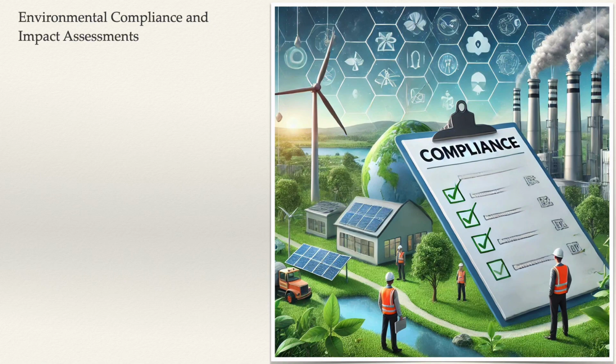2. Environmental compliance and impact assessments are typically conducted by the client before project initiation to secure route approval. For transmission line projects with significant environmental impacts, an environmental impact assessment (EIA) is often required. The EIA evaluates potential effects on air quality, water resources, wildlife, vegetation, and cultural heritage sites. This study is usually carried out by a consultant engineer based on the client's requirements. The EIA process typically includes A.